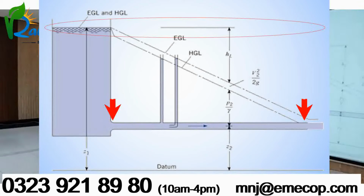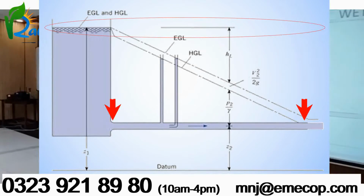Similarly here, the fluid has to spend some energy in order to flow from that point 0 to some point, for example, up to that point. So during that travel, it will lose its energy, and that energy loss is called friction losses. So the total energy line will include hydrostatic pressure, velocity head, and pressure losses.